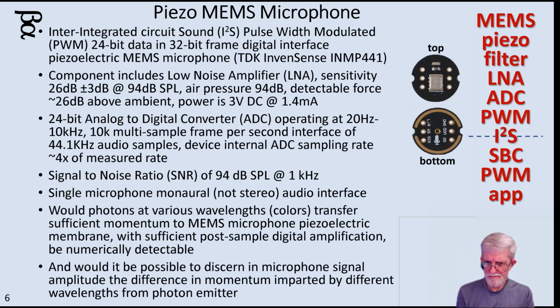So here's the microphone. The microphone itself is about the diameter of your thumb. Just think of it as a little disc about the diameter of your thumb. That's the printed circuit board. And then in the center of it is this little tiny chip. The top of the chip is sealed. It's kind of an air reverberation chamber. And then on the bottom of the chip, there is a little tiny hole. And that's where the air pressure goes in to make the piezoelectric effect work, to make it record the audio.